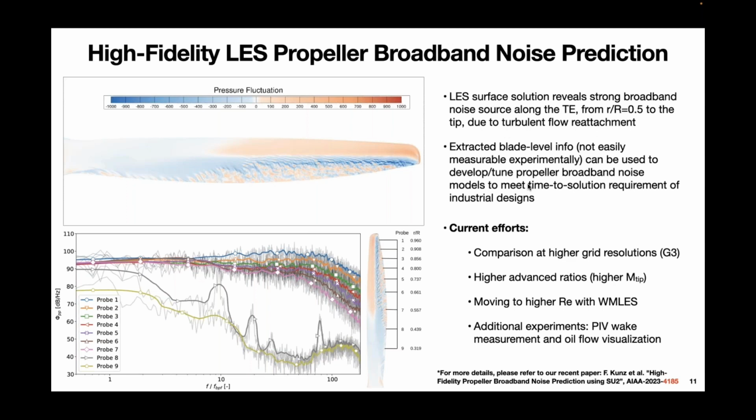To enable simulation at higher Reynolds number, we are planning to look at wall model LES as well. And from the experimental side, we're trying to do some PIV wake measurement and oil flow visualization to help cross-validate with the simulation.